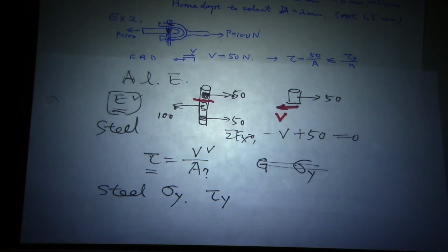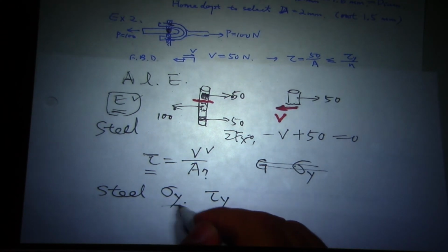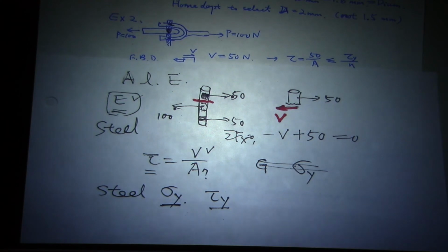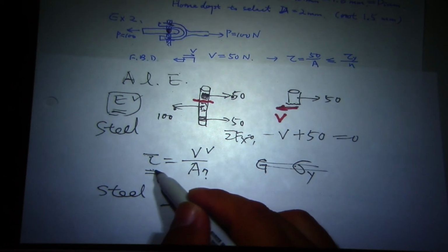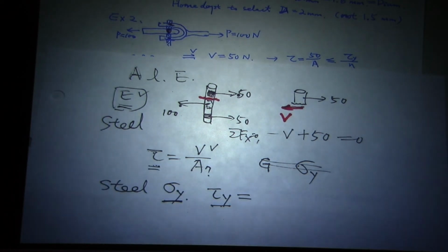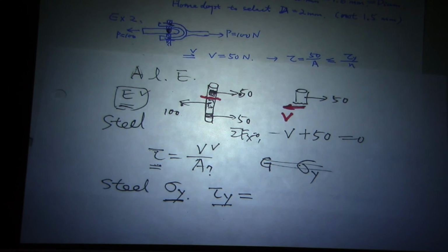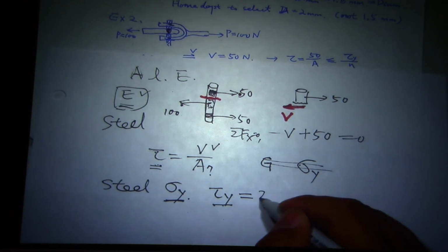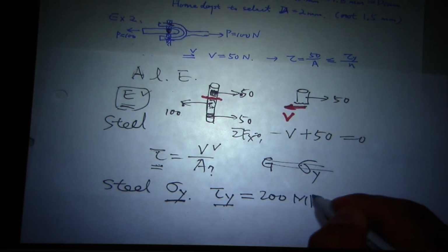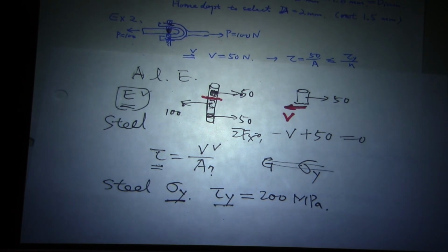So basically, for this material, I can check the menu, find out how high the stress can go for normal stress and for shear stress. So you find your F max. In this case, I don't care about the sigma y because in our situation it is tau. So basically, I found this one, tau y, from the menu. Okay, let's give a value. What's the tau y we find from the menu? Let's say 200 megapascal. That's for steel material, something close to that range.